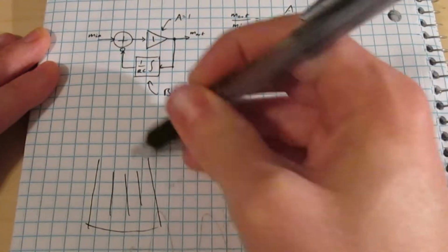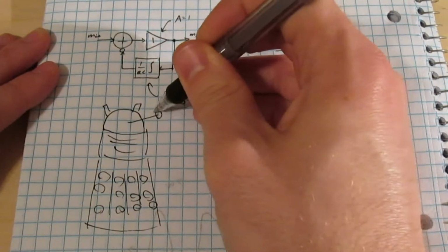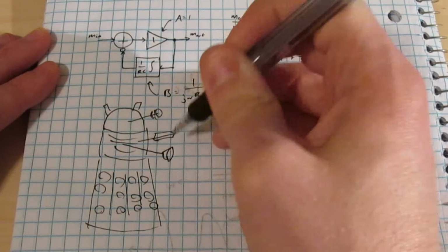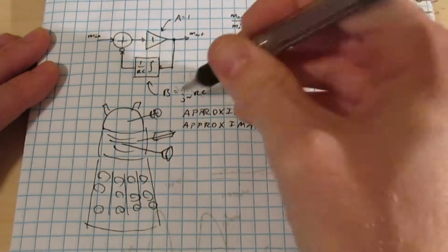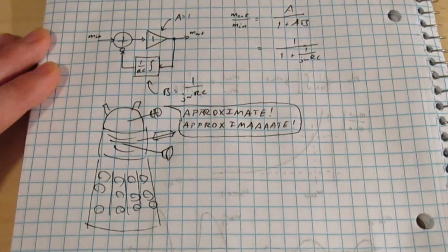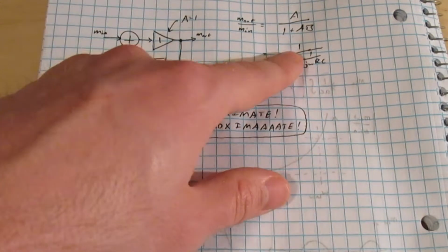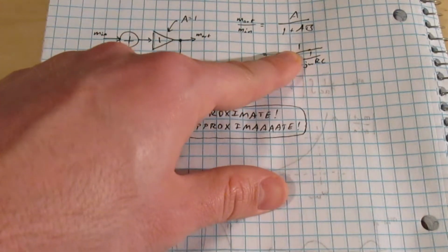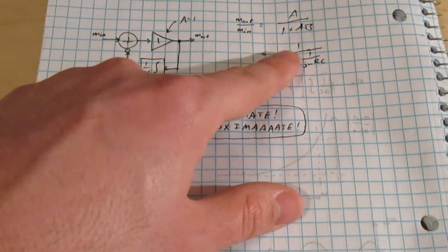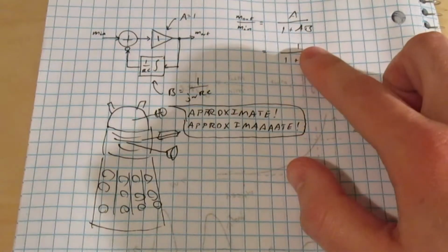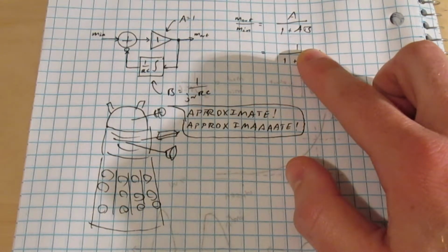This expression that we got for the gain of the entire system is a bit more complicated than the 1 over j omega RC. So if we want to actually plot the frequency response to see what's going on, we're going to have to do one of our favorite things to do as engineers, which is approximate. On one hand, it would be nice to get rid of this 1 on the bottom, because then that would turn into 1 over 1 over j omega RC, which is just j omega RC, which is easy to plot. Also, on the other hand, if we got rid of this 1 over j omega RC on the bottom, then it just turns into 1, which is also pretty easy to plot.